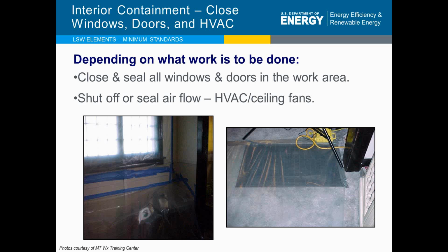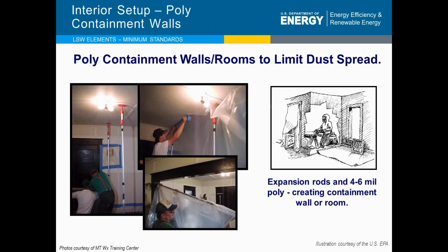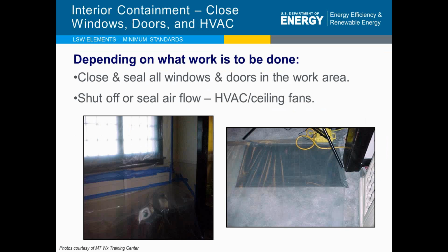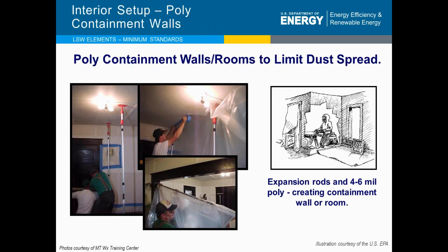So we're going to do maybe a combination of shutting off the airflow, shutting off the furnace during that time, or sealing over it so that we also do not get dust flowing into the ductwork, in addition to blowing all over. So just going back 2 slides, this 6 feet in all directions is required as minimum, and removing the furniture or covering the furniture is required, and the closing and sealing off windows and doors is required.